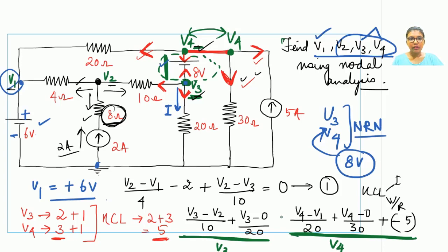Now one is required to club these two nodal KCL equations together to form the supernode KCL equation. So I'll club them together. These are the complete set of KCL terms for the supernode branch. Finally, we are supposed to equate it to 0. So with this, we have obtained our second equation as well.